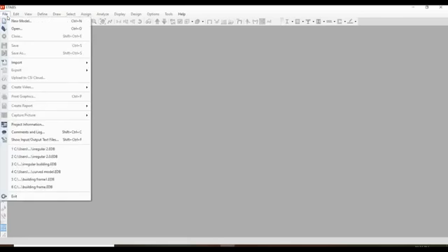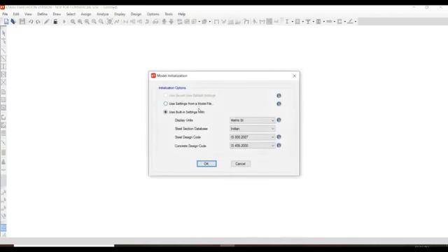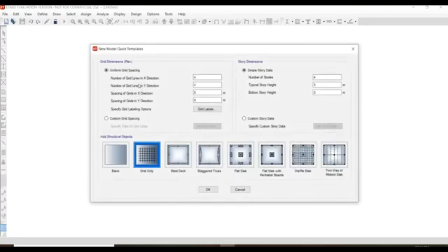Today we're going to see first we need to design the model. For designing the model, first open ETABS and open the new model. When you open the new model, you will get a pop-up, and make sure the settings are made accordingly. Display units are in SI system, the steel section database of India, and codes of IS 800 and IS 456. Click OK.